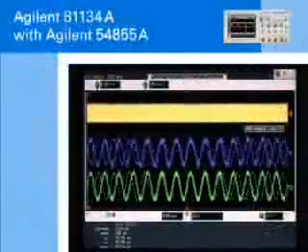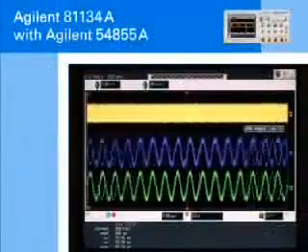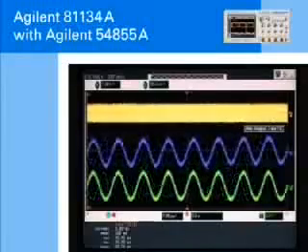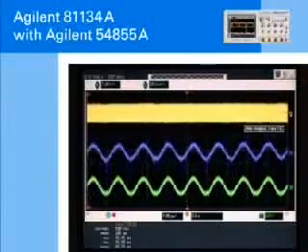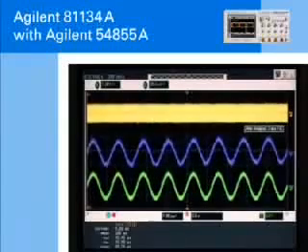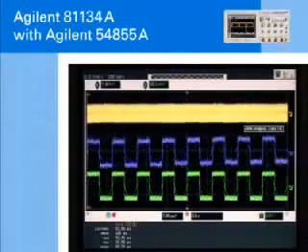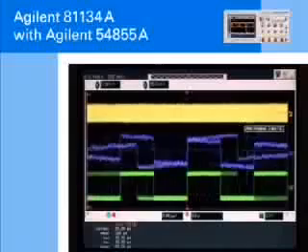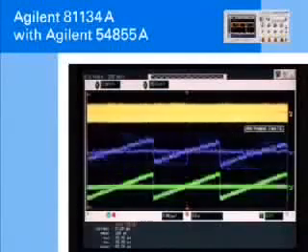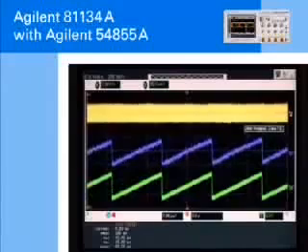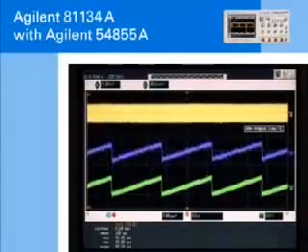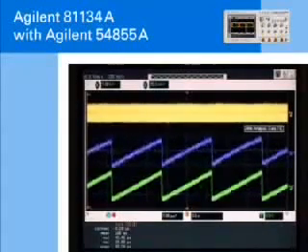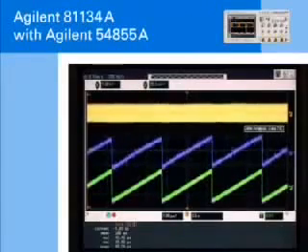Using the Agilent 54850A Infinium oscilloscope with the Agilent EasyJit software, you can see that the modulation source really controls the type and amount of the jitter generated. In addition, the oscilloscope shows the timing interval error waveform in blue. Below that, you can see the green waveform is captured from the jitter modulation source, which is also connected to the pulse generator's control input. These two waveforms are exactly matched, as the injected jitter is only defined by the voltage attached to the delay control input.